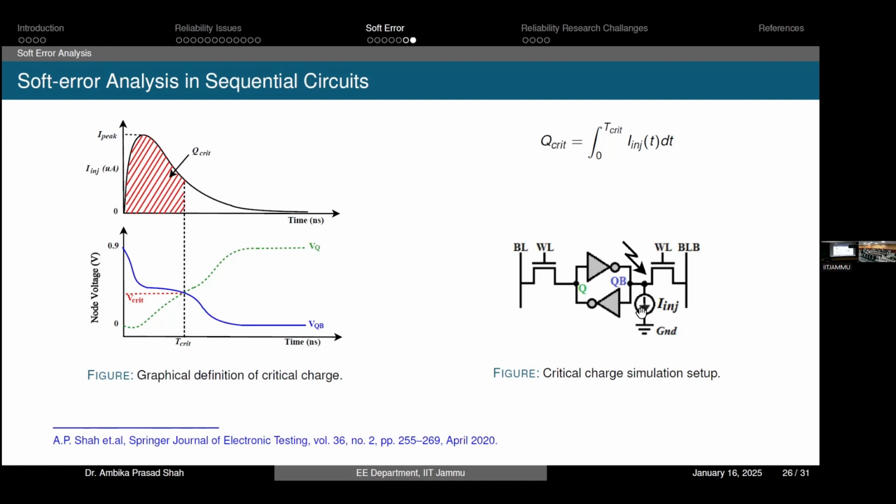Let us assume the chain of circuits I was showing: if that signal is used to turn on or turn off any device or module, then if one impulse passes through that circuit, it will turn that device on or off when it was not required. It should remain the same, but it will change its status. That can become a complete failure of the system because of that small impulse at a node. So we need to mask them, and a proper masking scheme is really required.